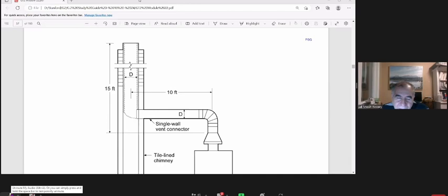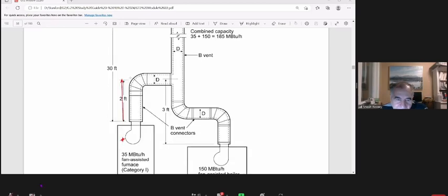So far we went through one appliance. Now two appliances. Look at this one, two fan assisted. Now we don't care about lateral anymore. Now the rise is important. How much is the rise? R1, R2, these two rises. When it comes as a combination, the height is the same. R1 is 2, R2 is 3.